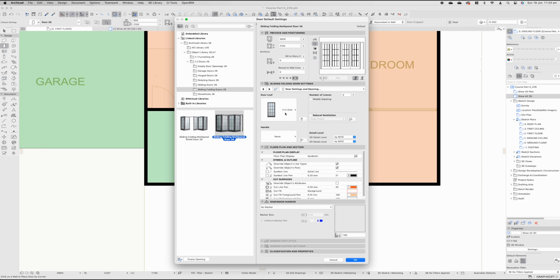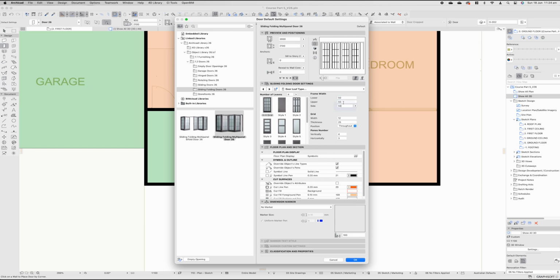So let's keep this HV grid on. Let's directly jump to the HV grid settings. We want to drop all of these to 50 millimeters and make it a very thin profile. Ideally, if we do it out of steel, we might even be able to get away with 40 millimeters, so we can drop that quite thin. Next, we want to change our actual panel grid layout. Vertically, we don't want any. We just want to hit that to 0, which will automatically default to 1.